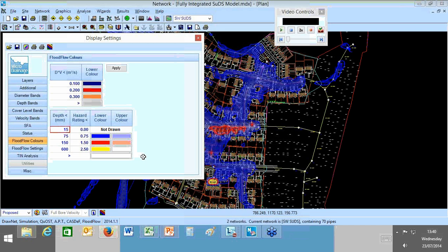Now the draft standards that are coming out, one of them that I've had a look at this week for the Middle East, is that what they would like is, well, two different depths really. One scenario is with some local roads, and they want the local roads to have no more than 100 millimeters of water depth, and that water should be less than 100 millimeters within an hour, if that makes sense.